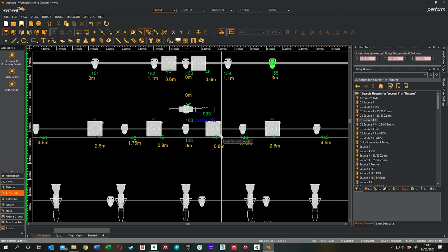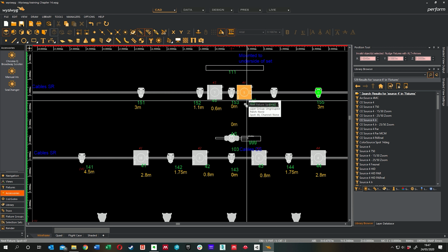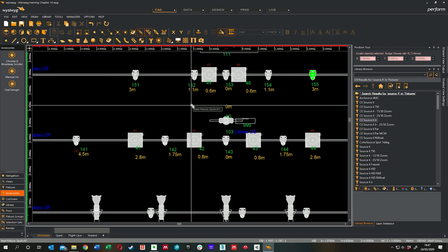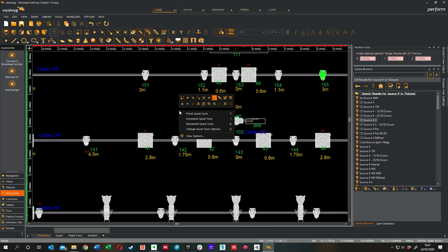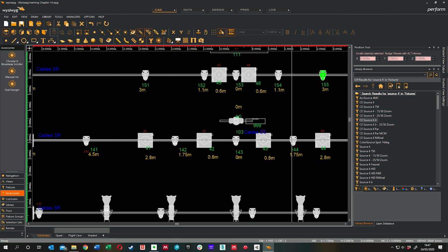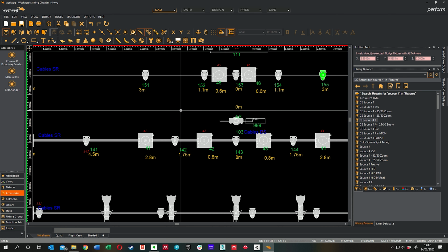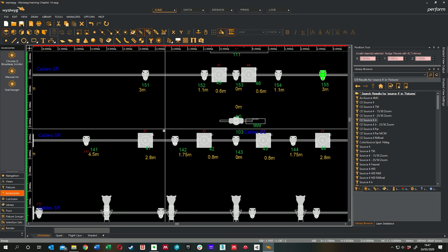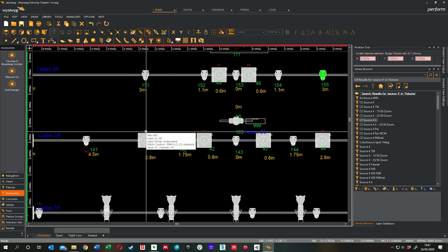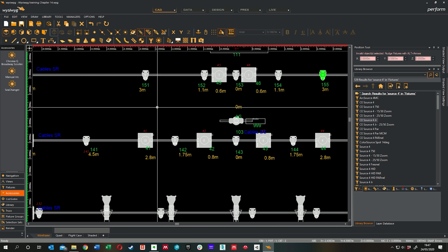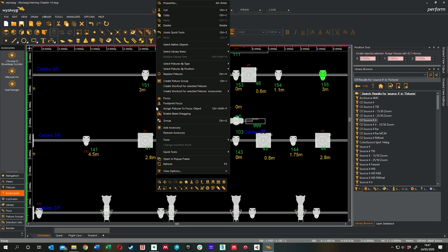And this is another method I use, is I'll just channel everything up like this. Particularly if I'm working with a lighting designer, I may have the channel numbers, but I might not have the patch from the chief electrician. So I'll do that, and then I'll edit this later in the data mode. I can just go through and just type in the patch. I'll literally just work my way through the spreadsheet on the one screen, and on the other screen I'll go through all the channel numbers and type in the patch manually. I'll show you how I do that when we get to data mode in chapter 5, which will be around about where we do it in lesson 33. We're going to look at the patch screen. But I'm going to go back and carry on doing it this way for the moment.